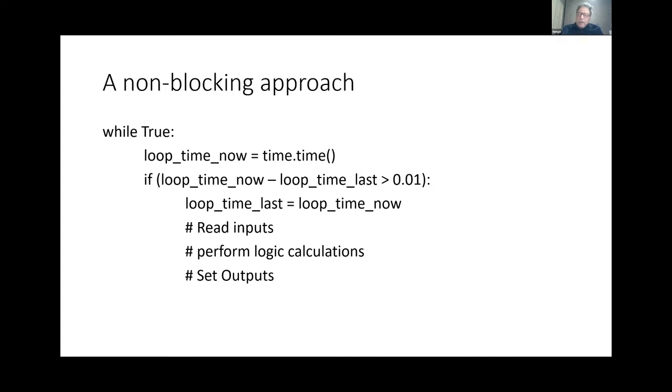Now that structurally has a real advantage: I'm not changing the outputs halfway through the logic, because historically, in relay logic, we had electromechanical relays. You'd have this concept called race logic, where things were changing on the run, and in doing so, it screwed up your logic calculations. So a lot of industrial PLCs work this way, where they'll read all the inputs in a slab, perform the calcs, and then write the outputs.